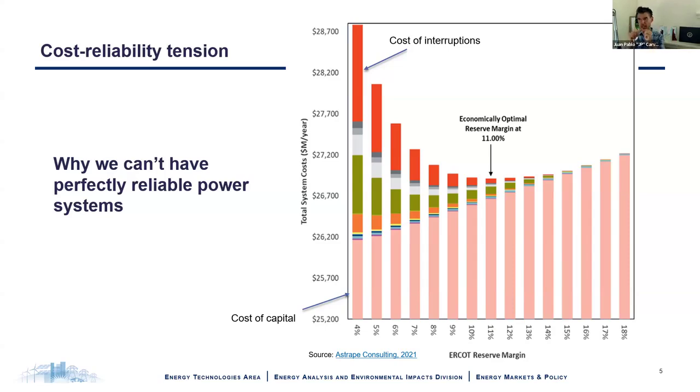And that margin can be moved depending on the season. As you know, in California, it's wildfire season, so I'm more likely to have a PSPS event than in the middle of the winter, and so I can adjust that reserve. These reserves apply in pretty much every single system, from the battery all the way up to the wildfire system. Let me add that for a vertically integrated state like California, even though you have an ISO/RTO, you still have integrated resource planning and vertically integrated utilities to some extent.